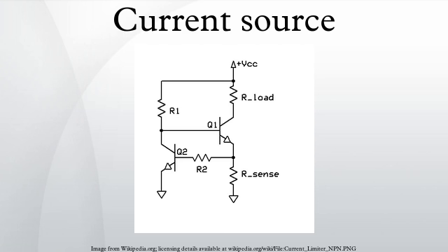Transistor current source with diode compensation. Temperature changes will change the output current delivered by the circuit of Figure 4 because VBE is sensitive to temperature. Temperature dependence can be compensated using the circuit of Figure 6 that includes a standard diode D in series with the Zener diode as shown in the image on the left.